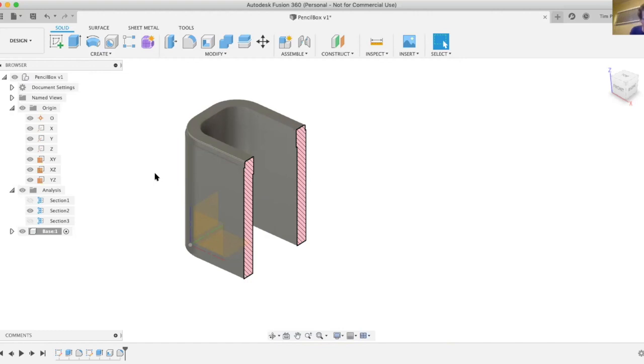And that's the way I typically prefer to do it. I see some people do it another way: they'll work in the positive XY plane, and then insert the plane of symmetry. They might use a mid-plane or something of that nature to create it so that it can follow, or they might use parameters. But I prefer to use the positive and negative XY planes to reflect my symmetry and have the origin in the symmetric center of the part. Got it. Okay. But it's more a personal preference. Okay.